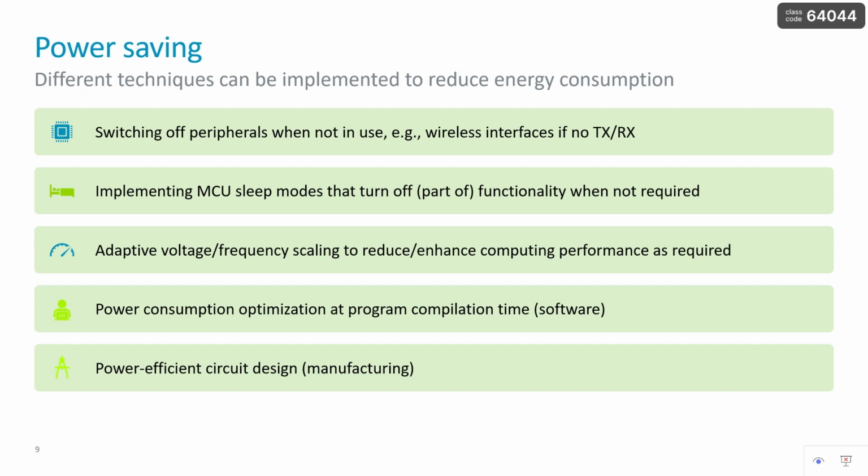However, if you take a look at your desktop, the desktop architecture is basically based on the Intel 64-bit architecture, which is CISC instead of RISC. It's complex instruction set computing instead of reduced instruction set computing. And when it comes to RISC, the large operations are processed in small and simple blocks, keeping the instruction set simple, which also helps in reducing the power.